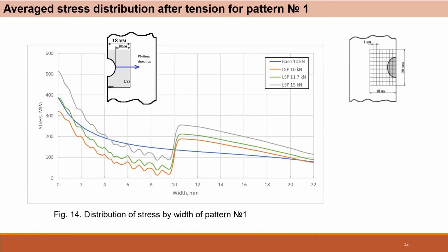For the first pattern, this load is equal to 11.7 kilonewtons, because we decided that the crack and degradation of the material comes not from the surface, and we try to estimate which residual stress will correspond to the base specimen. And for that pattern, the level of load is a bit increased, so we couldn't see fatigue life improvement for this pattern.